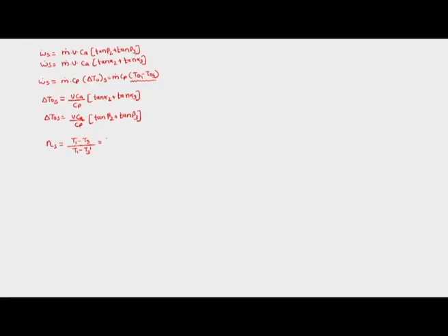We would also write it as T01 minus T03 divided by T01 minus T03 dash. So here we can take T01 minus T03 dash is equal to 1 upon isentropic efficiency into T01 minus T03. So the expression for T01 minus T03 is here. We will name it as number 1.